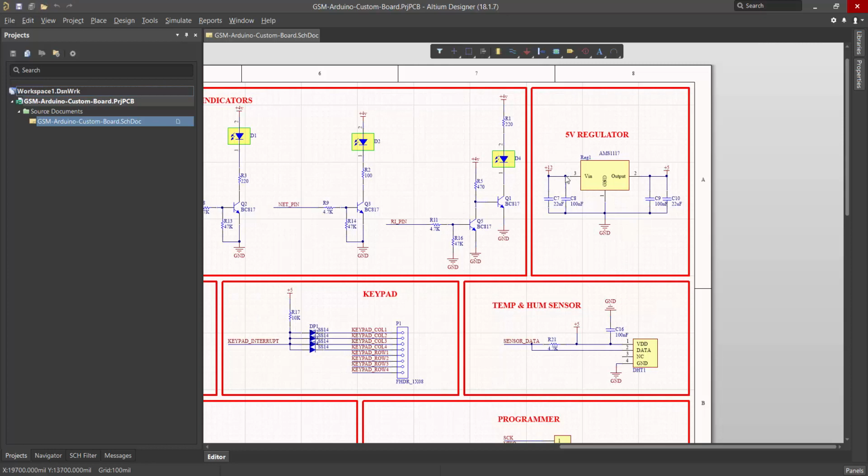So the power that will be consumed from our power supply is 12 times 2 amps, and it will be 24 watts, right? This difference in power will be converted to heat. It should be wasted, and it will produce a lot of heat in this component. This component will be very hot and will be damaged over time.